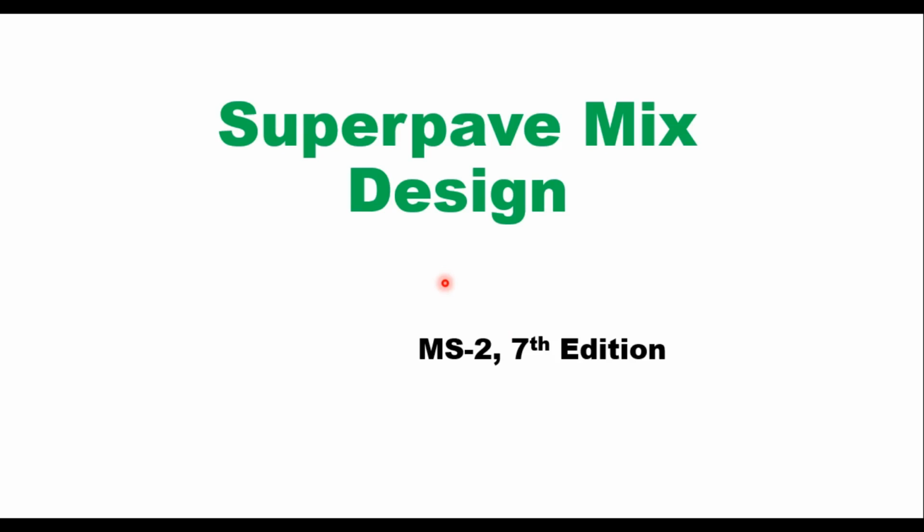Hello friends, today we will discuss the Superpave mix design procedure as given in MS-2, 7th edition. This design procedure was the direct outcome of the Strategic Highway Research Program, SHRP, and here Superpave stands for Superior Performing Asphalt Pavements. This procedure was developed to replace the Hveem and Marshall methods.